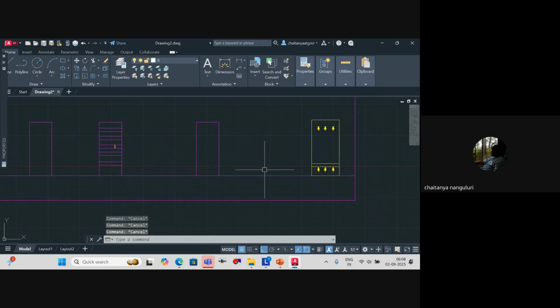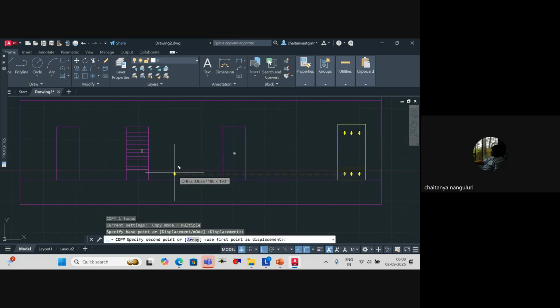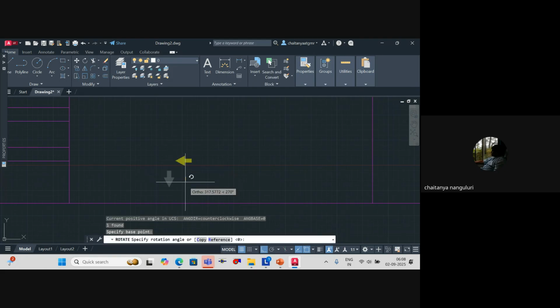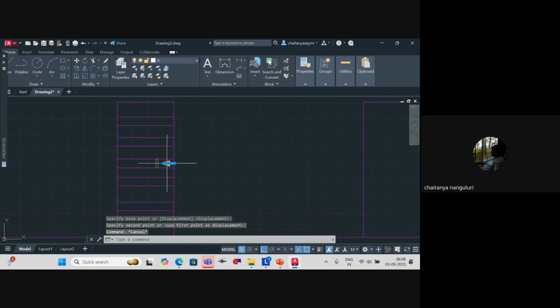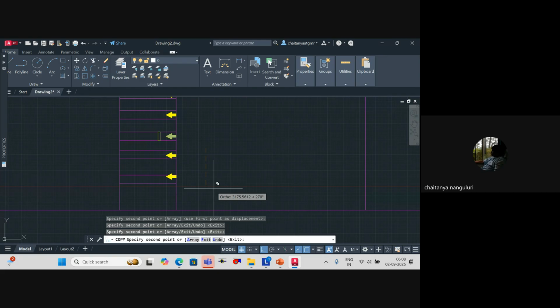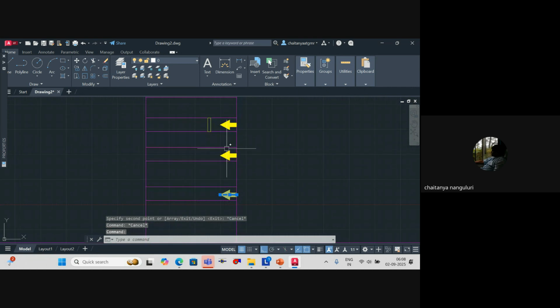Generally, the direction of the air that's absorbed by these is something like this, let's say. That will be told to us by the manufacturer. Let's say air is going into every server rack like this. Clear? In this case, the air is going like this, and then it will pass over the electronic PCB, and from here the air will be coming out again. Hot air will be coming out.